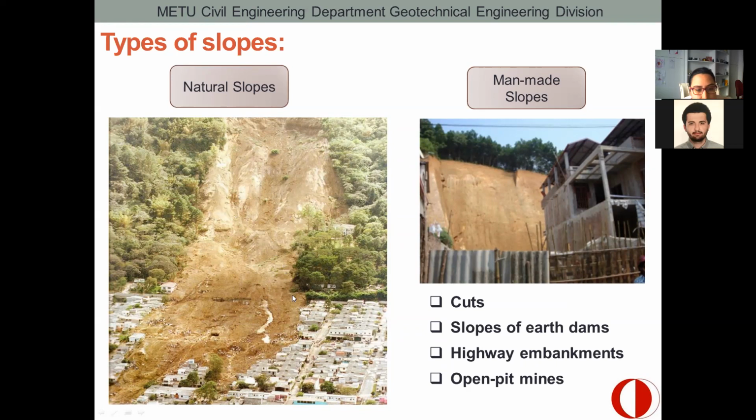Okay, and if their factor of safety is not acceptable, if we think that the slope can fail, we can create or design some sort of measures to prevent that instability conditions. So this is not something that we designed. Okay, the only thing that we can do is to calculate the factor of safety against failure.